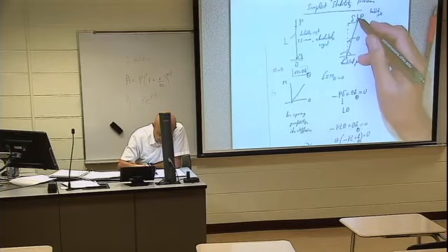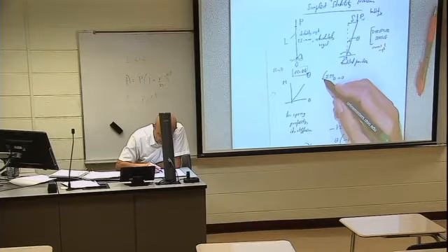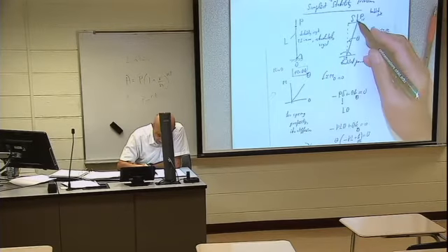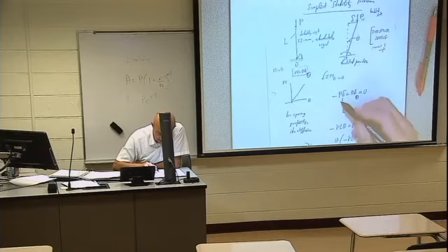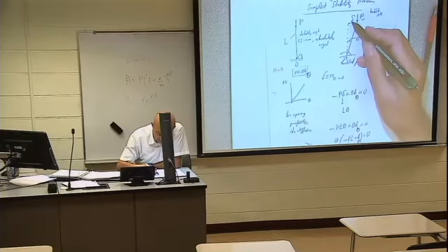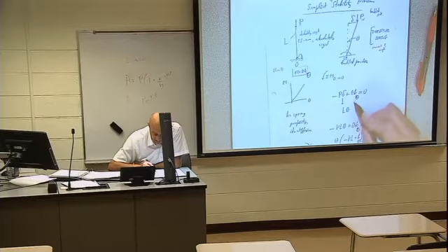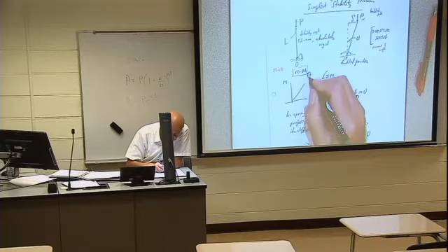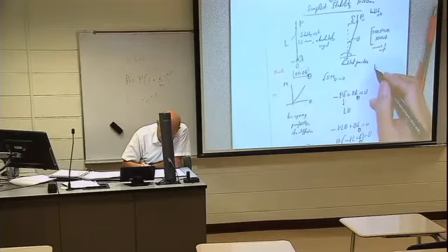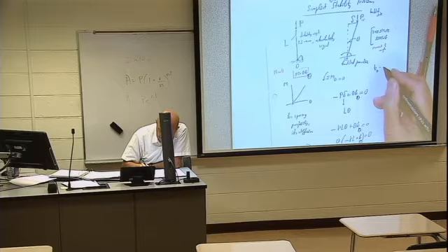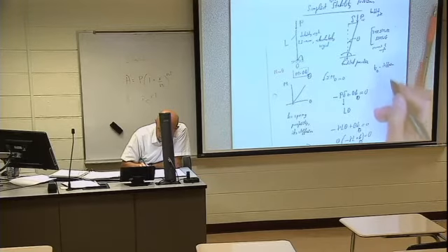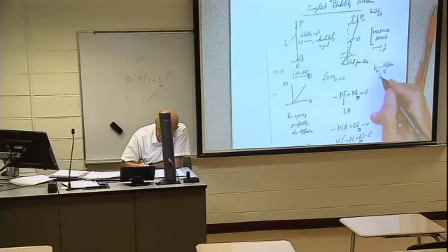And look, this is a positive direction. This load gives me a negative contribution: minus P times delta. Here the bending moment is positive, and it is theta times K theta. So I call it K theta. So K theta is the stiffness of the torsional spring.